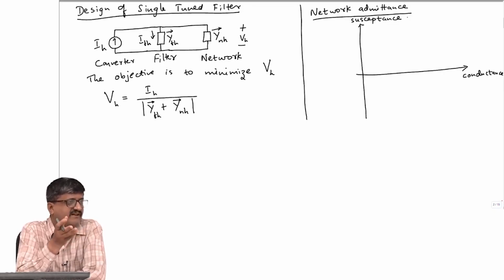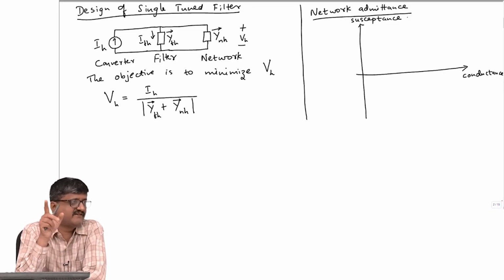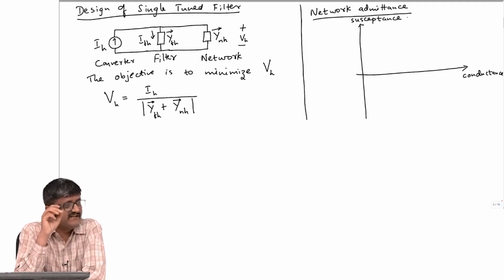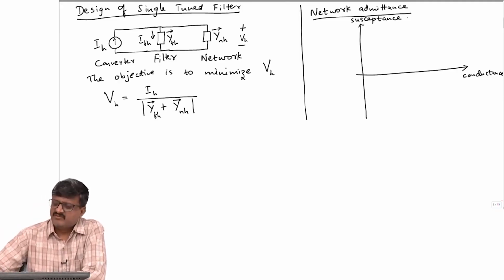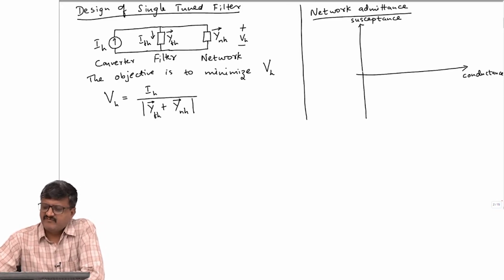If you take a transmission line, it is not just inductive, there is a shunt conductance also, and a shunt capacitance as well. Whenever there is a capacitance, there is a possibility of positive susceptance. So, it can lie in the first quadrant and the fourth quadrant. It does not lie in the entire first or fourth quadrant. It can be shown that it lies in this sector.